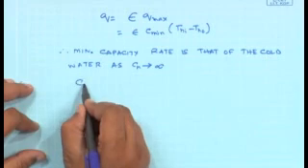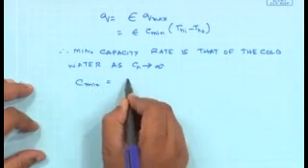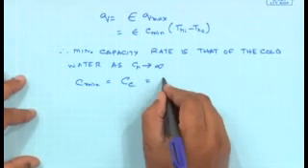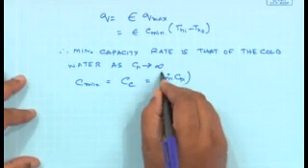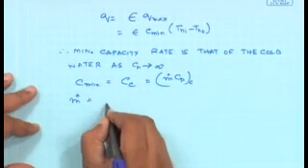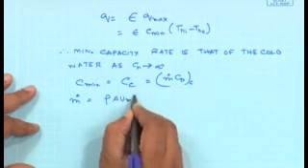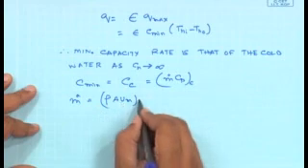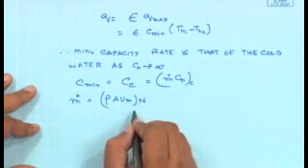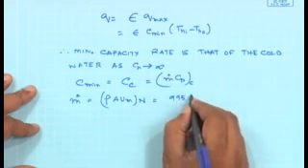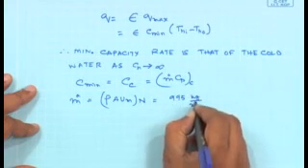So with CH tends to infinity, my C minimum is going to be C of the cold water, and C of the cold water is m dot Cp, all related to cold water. So what is m dot? It is rho A u. This is the flow rate of water through one tube. I have n number of tubes which are present in here. So I am going to write the rho as kg per meter cube.